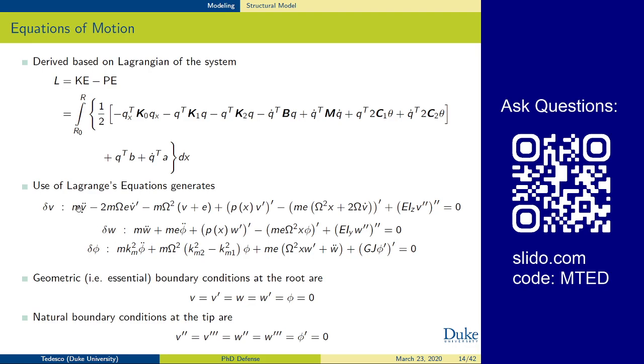We see basically our mass times accelerations, or our inertias times accelerations. We see our typical Euler-Bernoulli beam theory fourth derivatives. We see some terms such as this one here that is due to Coriolis effects. We notice that there are also some terms, this E here, which is basically an offset between the center of gravity and the axis of rotation. And then finally, we see this P term. The P term is effectively what we call a centrifugal stiffening term. This is because as it bends, it's going to tend to want to be pulled inward, which is actually going to stiffen the beam in that direction.